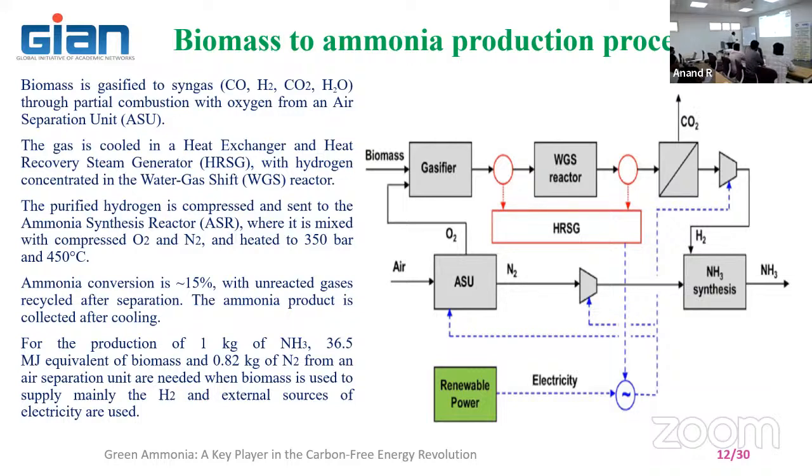Whereas for finding out the calorific value of the synthetic gas, syngas, we can take it to a GC. We have the onboard GCs available. You can use it to find out different hydrocarbons, and then find out the calorific energy content, or you can go for the Junkers gas calorimeter.